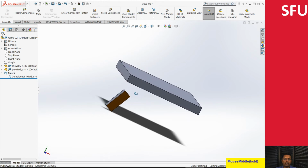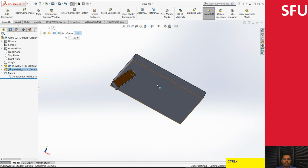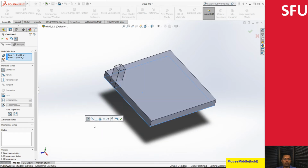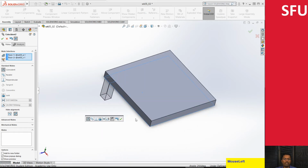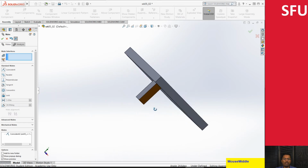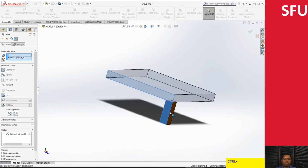Here what I can do is click on the top and then the bottom over here, and then mate, select mated constraint. So this is actually coincidental, and then they're mated. If I flip, my table is going to have a leg protruding out, which I don't want. Flip it again. Now it's assembled properly. Say OK. For the most part, the table is done. I can just select this face and this face, and then it automatically inserts a coincidental constraint. Then we say OK.